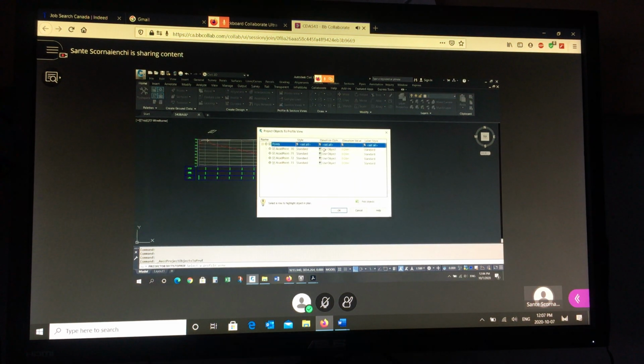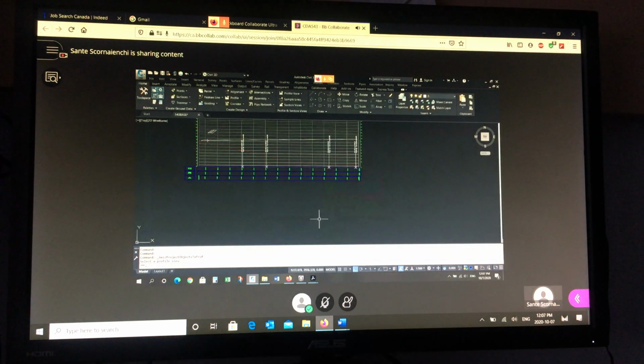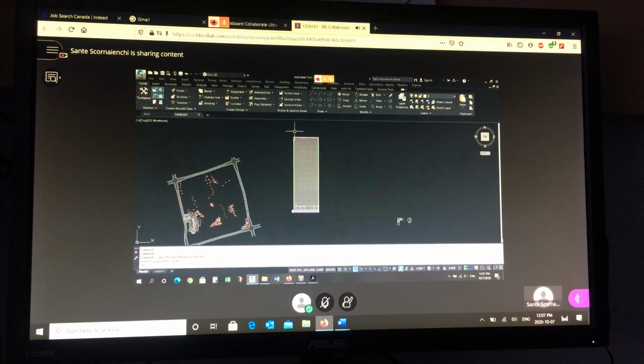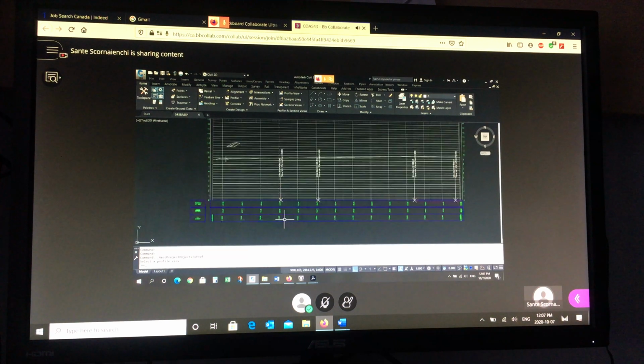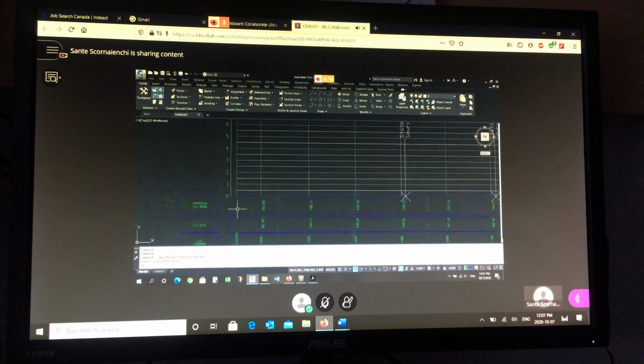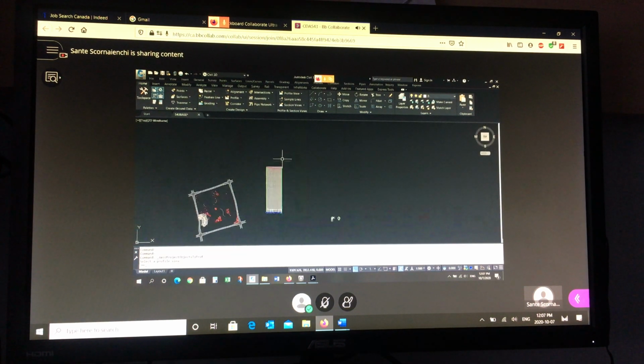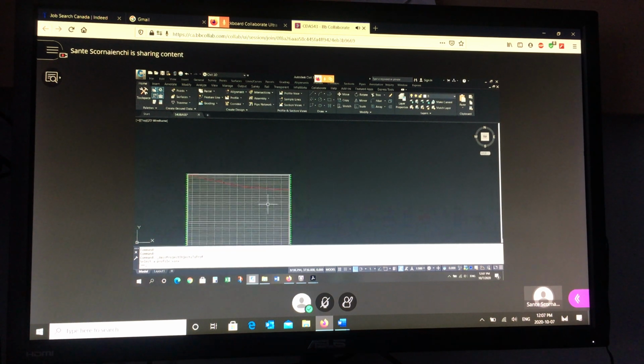Now those points in the plan are AutoCAD points. And I snapped the locations where the elevation is 0. See, the elevations are all 0? If I say OK, so this is what not to do. Watch what happens if I say OK. Look at my grid. See how big it got? Because my design is up at 100 and something, but those points are at elevation 0. So now I've got these points way down here, and my design range elevations are way up here. So don't do that. Here's a trick.